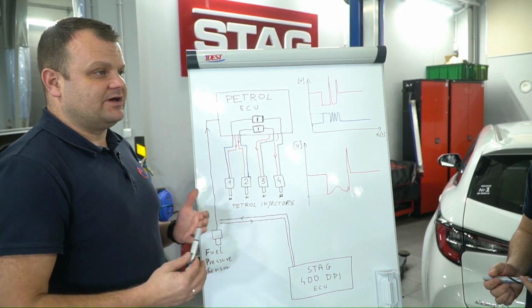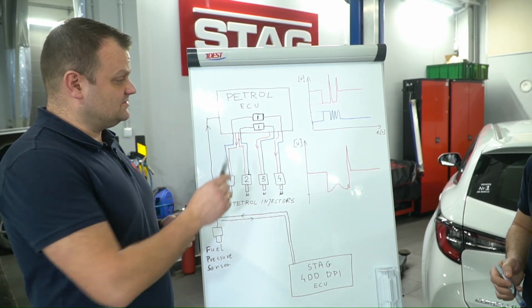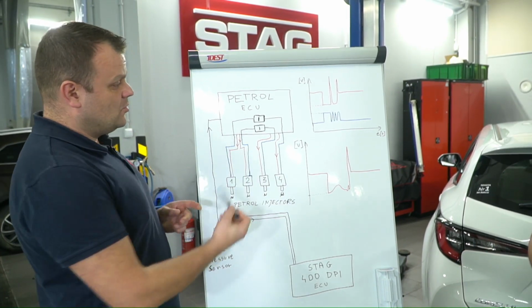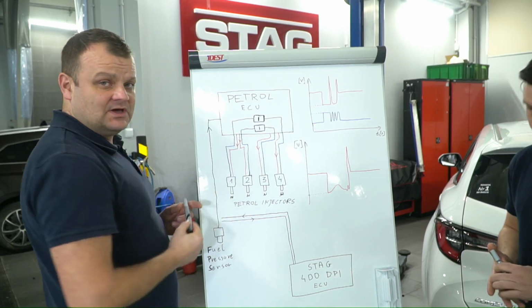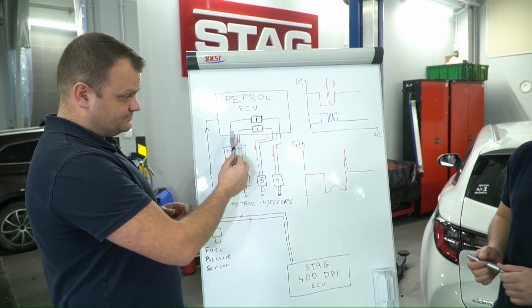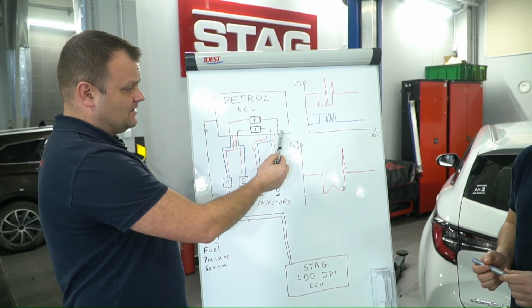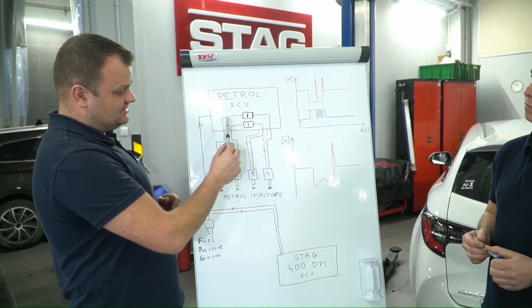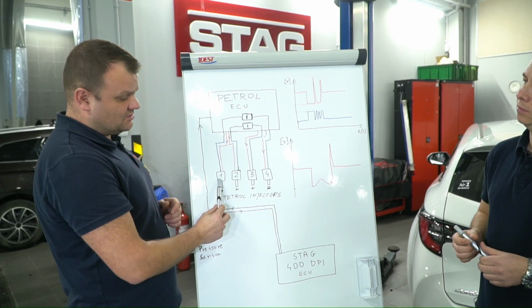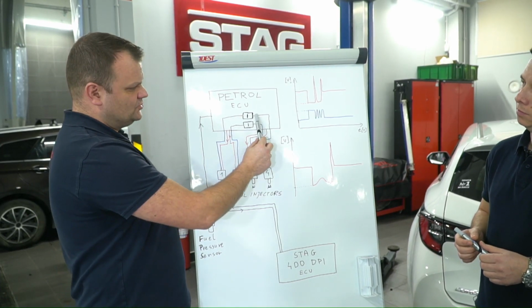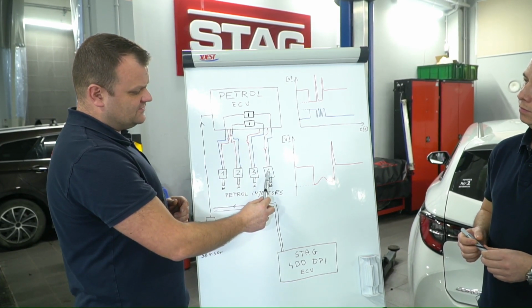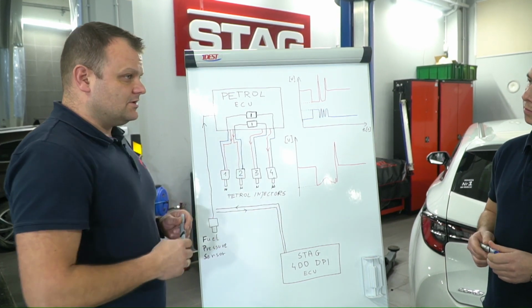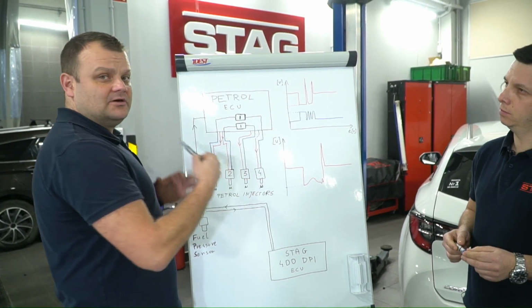I think in about 90% of cars the Petrol ECU is similarly constructed, where one single inverter delivers this high voltage to 2 separate injectors. It means that one output of the inverter is connected with injector number 1, and the second output is connected with injector number 4, and they are working in pairs.